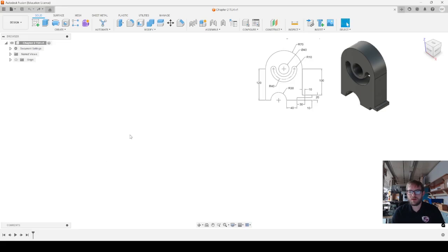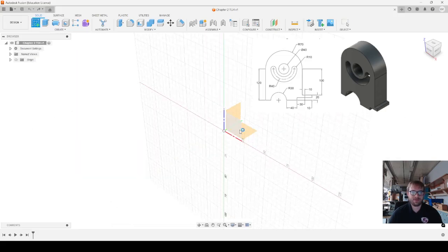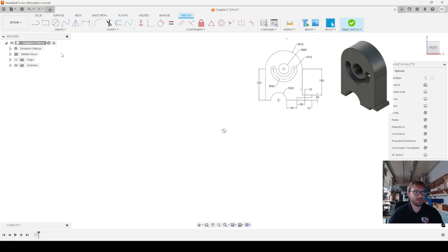But when you are designing parts to be machined or done on different types of machines, you might want a different orientation. When you are in the machining tab, you can redefine some of those planes, but it's kind of nice to just have the file created in the most natural way, or in the way it's going to be machined, whichever seems better to you. But we'll just follow along with their orientations. So I'll do it on the front and we'll get started.